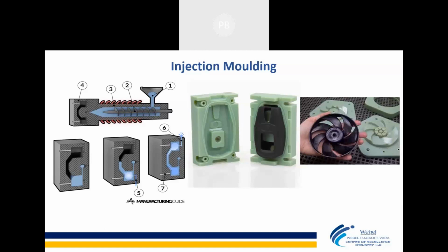So injection molding is a process, worldwide, the biggest process for high-scale production. Where your quantity requirement is in lakhs of pieces, maybe 2 lakh, 3 lakh pieces, injection molding is the best suitable way of doing that. With injection molding, there is a core and cavity, like there is a die portion.